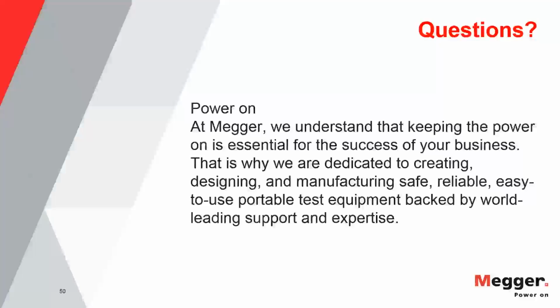Any rated voltage. The limitation, I would say, is that you have to make sure that the cable has a shield on it. So your very low voltage, your 480 volt cables, are not mechanically constructed in a way that would be conducive to PD testing. But as long as the cable has a shield on it, so your 5 kV rated cables and above, you should be able to do some PD testing on it. With the lower voltages, though, some of your signals tend to be smaller. So if you're in a very noisy environment, you may not be able to detect the emitted signals. But generally speaking, pretty much anything with a shield on it, your 5 kVs and up, should be useful for doing PD testing on.